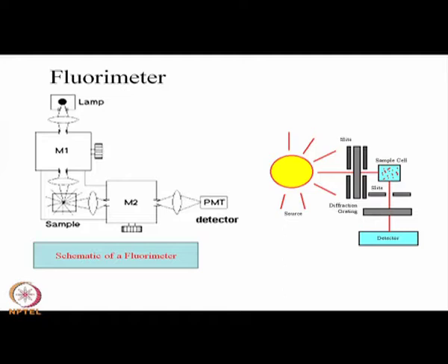So, then what we do? With the help of another dispersion medium, we measure different components. I mean, using this dispersion medium, we allow each frequency one after another to the PMT, and then the PMT measures. PMT means it's a detector, photomultiplier tube. It's like a photocell kind of thing, means more light, more current, so more signal that way.